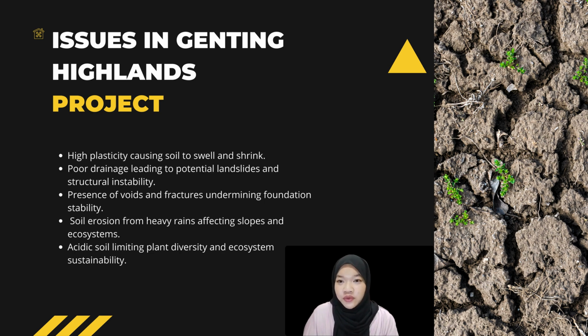Assalamualaikum, my name is Nur Aimani Huda binti Azmi and I will be presenting about the problem and solution for both projects. In Genting Highlands, the primary issue with clay soil are its high plasticity, poor drainage, and presence of voids. The soil's tendency to swell and shrink with moisture changes leads to landslide and structural instability. Poor drainage exacerbates this problem, especially during heavy rain. Hidden voids and fractures in the soil further compromise the foundation stability.